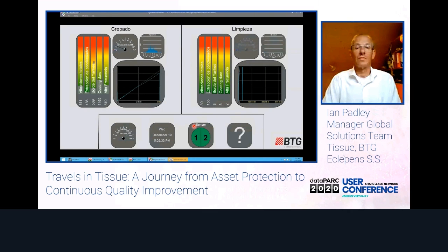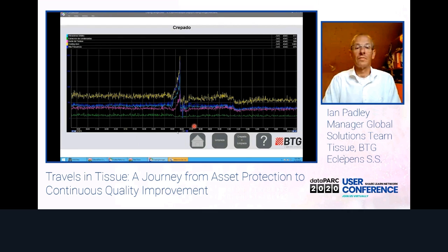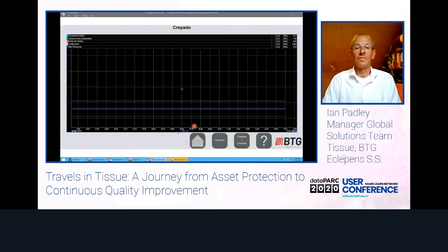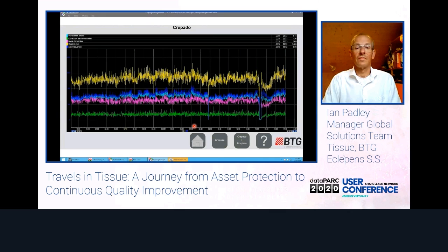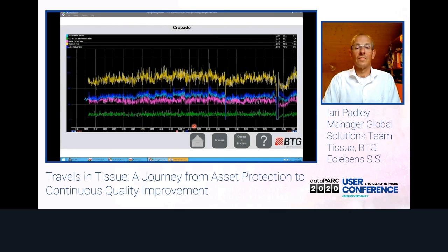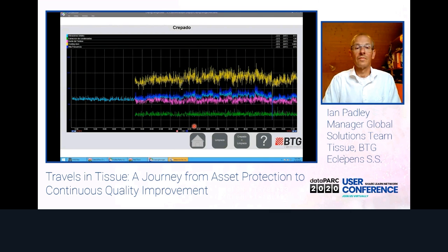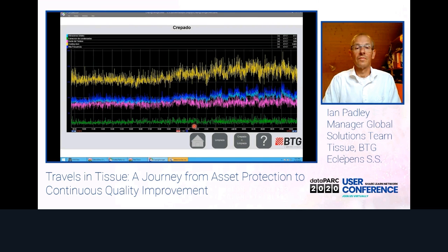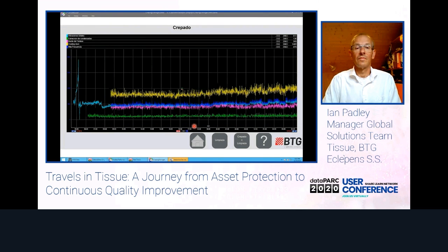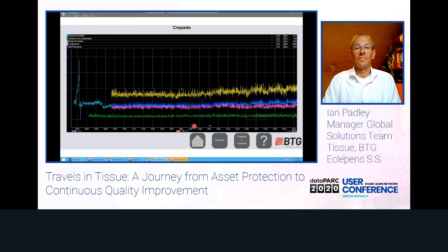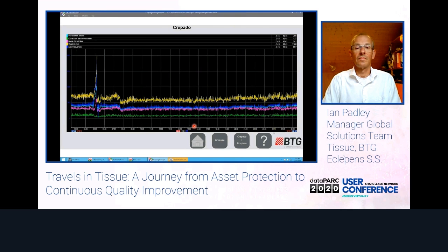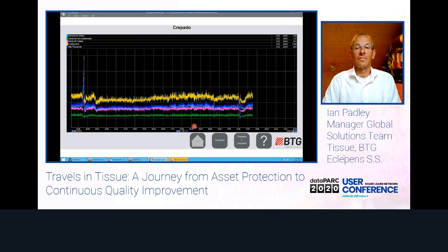The trend view has saved my position from before, so here is the event again. I can reset the view by clicking here. I'll scroll back to the event, and then I'll double the scope to see everything that has happened since. Vibrations have been steady ever since, and I can see over on the right 2 times when the blade holder was unloaded again. This first one is when the blade was changed.